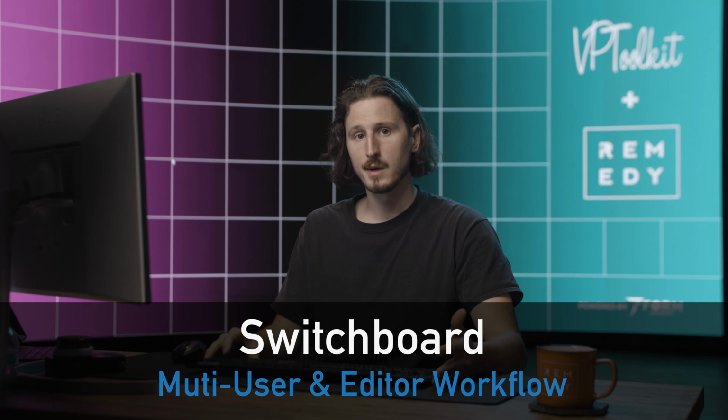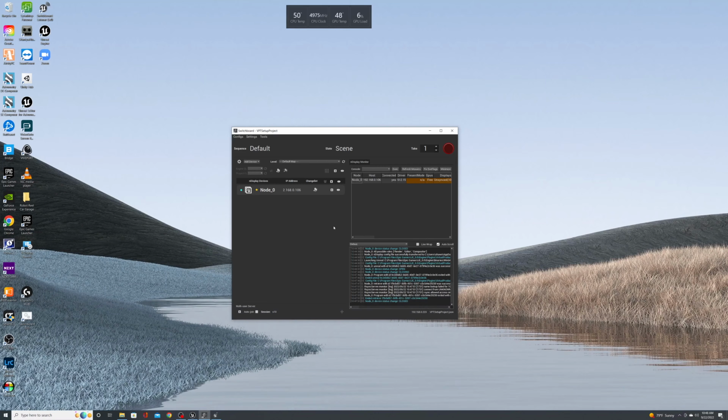So once we've tested our nDisplay projection and made sure that everything's rendering correctly, we're going to set up multi-user, which is going to allow us to control our nDisplay render from an editor. We're also going to set up Switchboard to control the instance of Unreal Engine that we're going to be using to edit our scene in nDisplay.